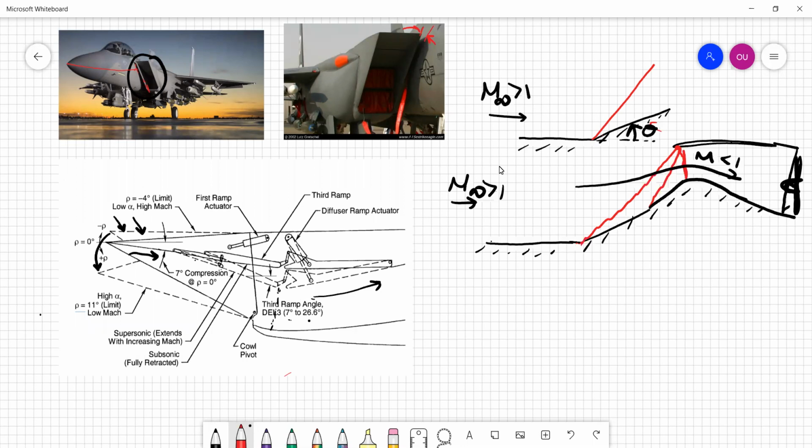We want that to live outside the inlet, so we separate the intake a little bit out. This is more or less the boundary layer thickness here. Anyway, we will talk more about it in the topic of boundary layers. But in the context of oblique shock waves, this is one very direct application of the oblique shock wave knowledge that we will learn in this class.